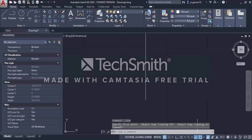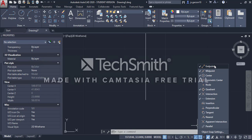This is one of the most important options, called the snap cursor. This enables you to automatically snap to different points of the lines. It can be endpoints, midpoints, geometric centers, points, quadrants of a circle, or even just any line. So if you want to optimize your drawing performance, you can turn them on and turn them off.